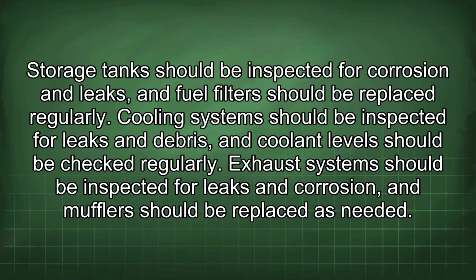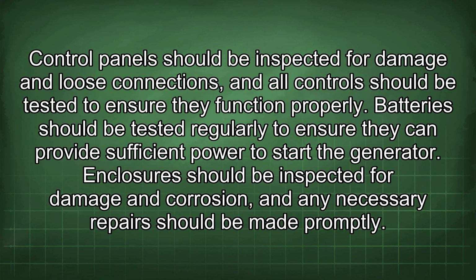Cooling systems should be inspected for leaks and debris, and coolant levels should be checked regularly. Exhaust systems should be inspected for leaks and corrosion, and mufflers should be replaced as needed. Control panels should be inspected for damage and loose connections, and all controls should be tested to ensure they function properly. Batteries should be tested regularly to ensure they can provide sufficient power to start the generator.